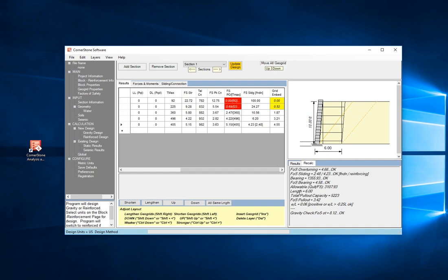But I don't have a lot of problem with it, because if I look at the factor of safety of pullout, of total pullout, there's my failure plane, there's my earth pressure wedge in here pushing forward. I've got this grid, that grid, this one, and this one, as well as base friction resisting the force behind it. So are the grids going to pull out? Probably not. I've got a total pullout capacity of 5,200 pounds per foot, or a factor of safety of 3.42. So in most cases, I'll leave the grid shorter. By engineering judgment, this wall is going to perform well.